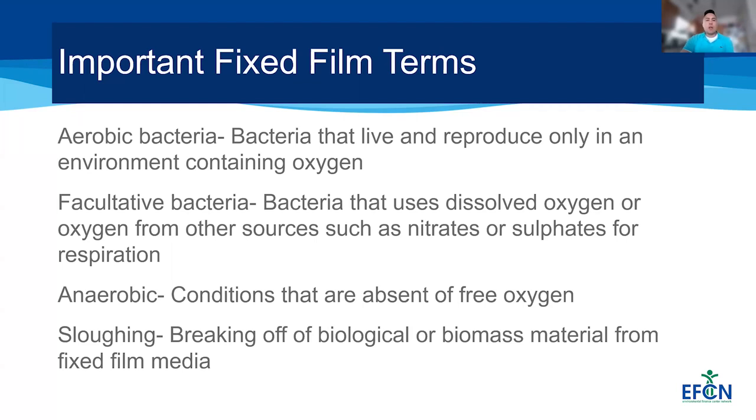Then the final term that I want to talk about is sloughing. Sloughing refers to the breaking off of biological or biomass material from a fixed film media. And this material is usually collected in the effluent of the fixed film processes and settles in a secondary clarifier.